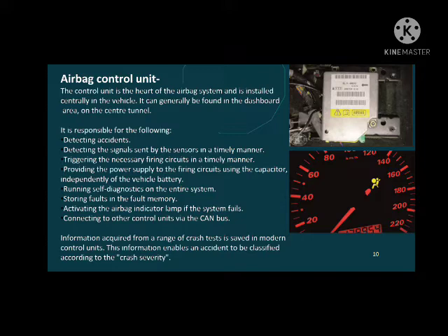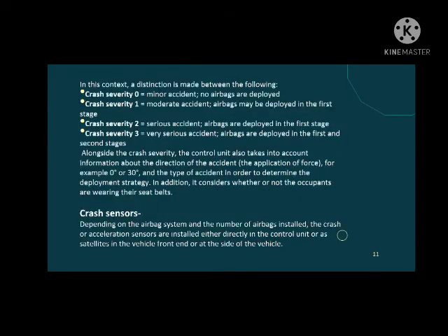In modern systems, the structure of the airbag is depicted in the figure. An airbag consists of a sensor that detects the frontal collision and an ECU, electronic control unit, that decides whether to deploy an airbag or not based on the signal from this sensor. An inflator produces gas. These structures are shown in the figure. And the bag inflates to protect the passenger and the driver.